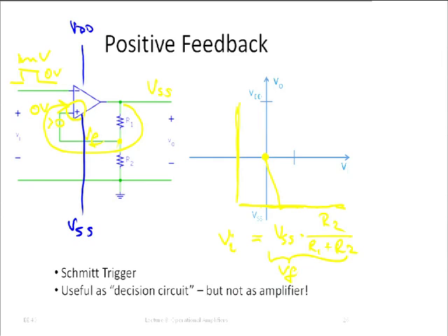Once they're equal, doesn't the output drop to zero? Okay, maybe then the output drops to 0. Yeah. Okay, so there is just one point when the output drops to 0, and then we would be at this point. And if you then make the input Vi just a little bit more negative, then we go all the way the other direction. Wouldn't the output dropping to zero make the difference across the inputs... and so it goes all the way? Yeah, that's right.